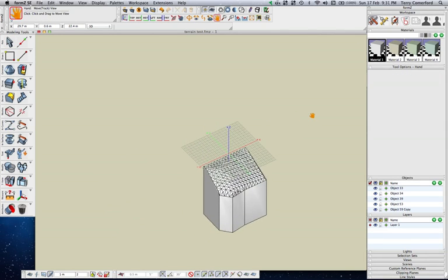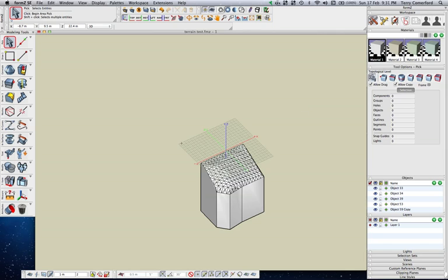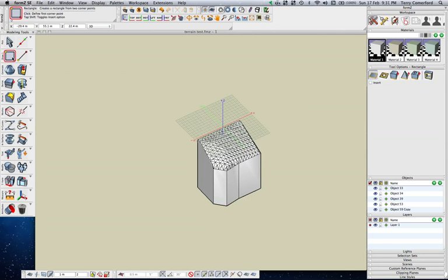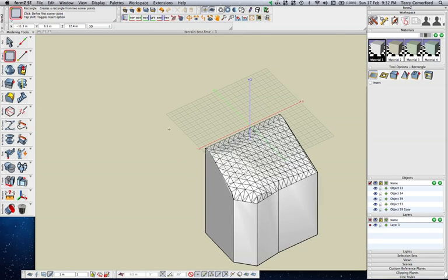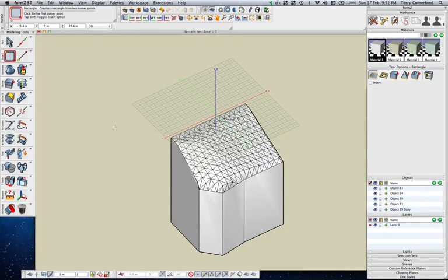Okay, so I've got this reference plane up above my topography now. Now I want to go back to watch how I try and draw shapes. My reference plane changes as I hover over shapes, but if I hover outside, there's my last reference plane that had no assignment to any particular face. Now if I press my F5 key, if I hover over faces now, this reference plane has been locked in place, so that's the reference plane that I will use no matter what I do.